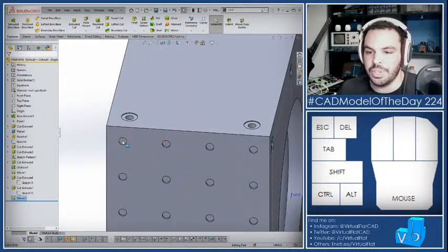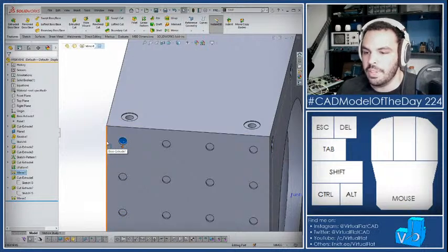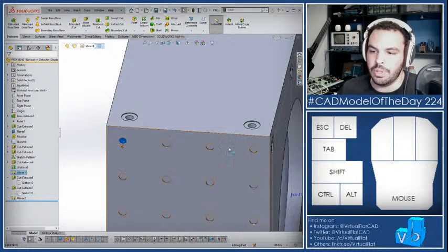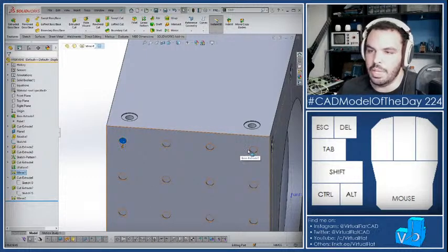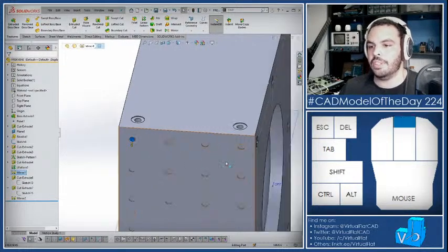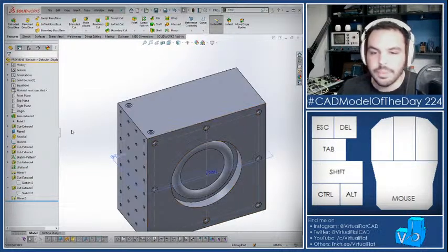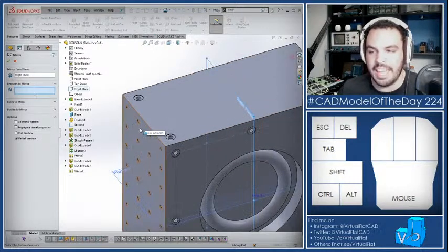Yeah, I measured the center of the circle to the edge, and I found out that was 15, excuse me, versus the dimension I specified here was 10, and that means that over the 3 spaces that there are, it drifts by 5 millimeters, so to say, and that means every space needs an extra 5/3 of a millimeter. So that's why I added it to that, and it fixed up the pattern. Yeah, that's like a nerd math trick that I just so happen to know.